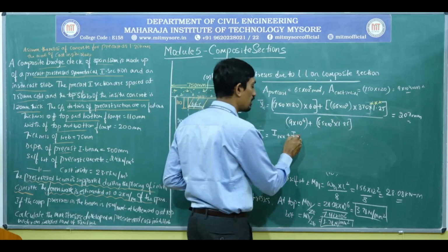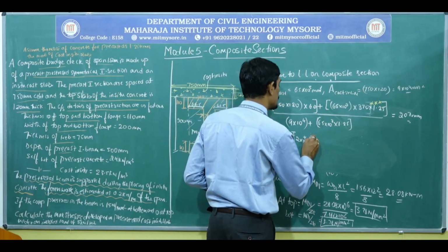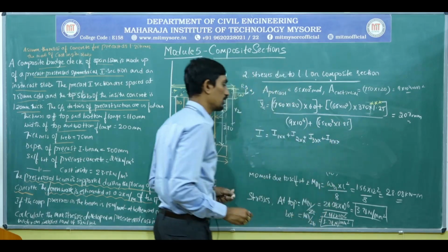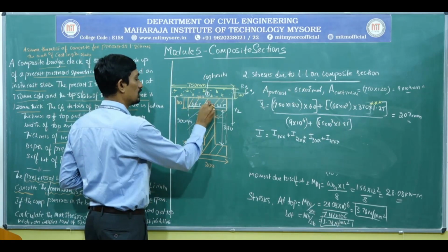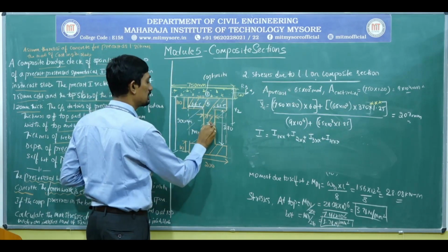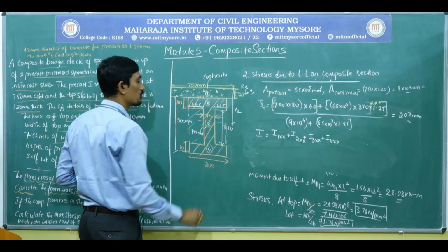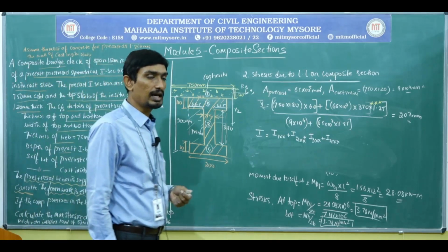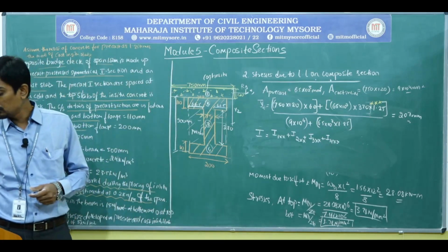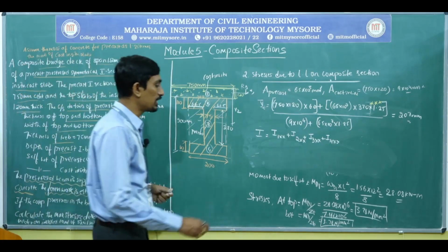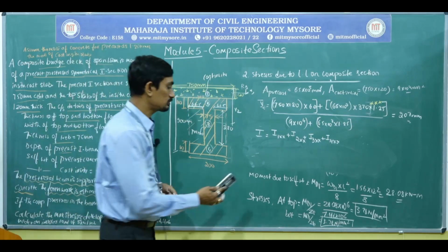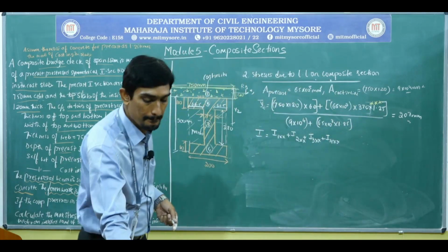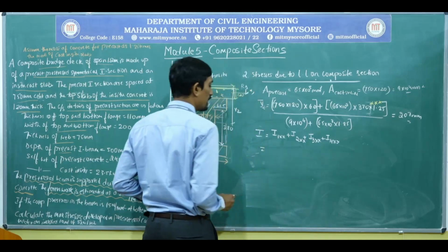Hence, moment of inertia of the second section about the centroidal axis, moment of inertia of the third section about the central axis, moment of inertia of the fourth section about the central axis. So this is 1, 2, this will be 3, and this will be 4. So 4 rectangles. I think in basic elementary class you people have done this. The same thing I am going to repeat here. So now first let me consider this. Let me go ahead with the first, I1XX.